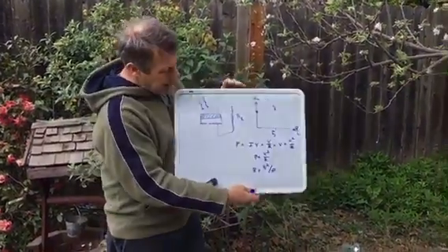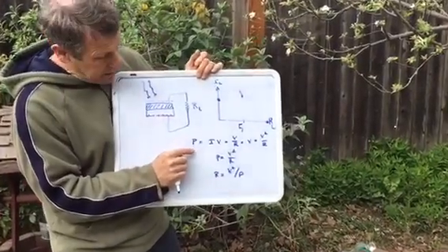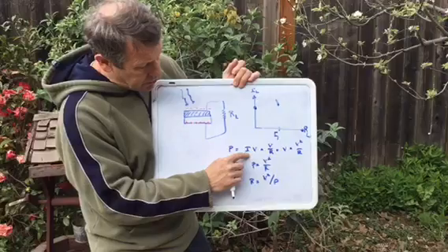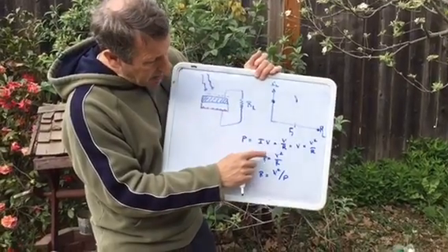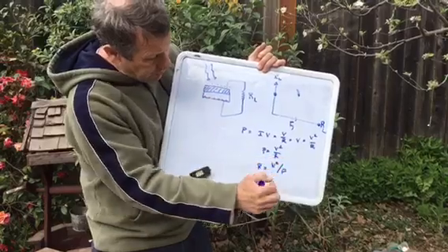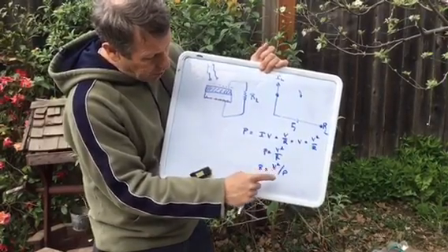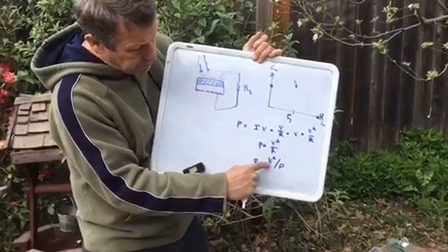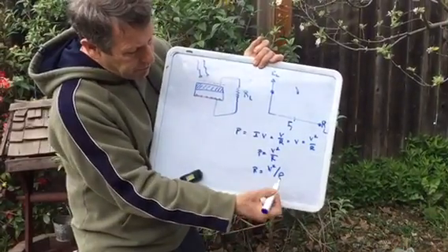Okay, so here's the math. For a straight DC circuit, the heat dissipation or the power production is the current times the voltage, and that current is V over R, so I got V squared over R. In other words, power is V squared over R. Do a little bit of rearrangement and you get the resistance is the voltage squared over the power.